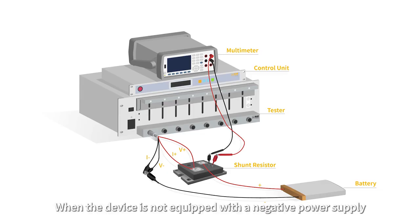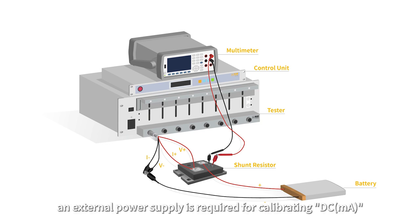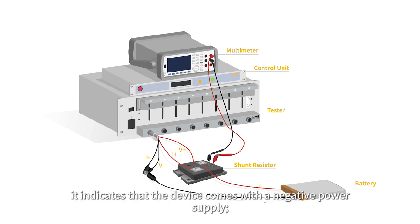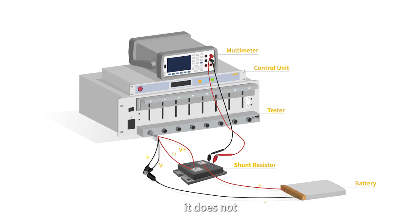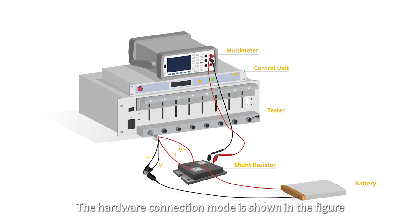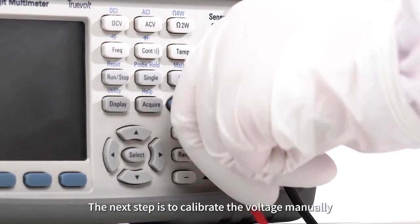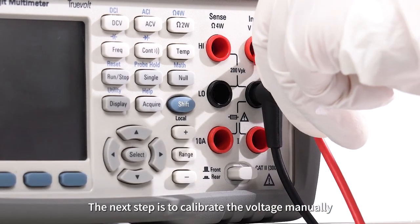When the device is not equipped with a negative power supply, an external power supply is required for calibrating DC milliampere. If the device serial number includes the letter F, it indicates that the device comes with a negative power supply, otherwise it does not. The hardware connection mode is shown in the figure, and the software operation is the same as calibrating CC milliampere.